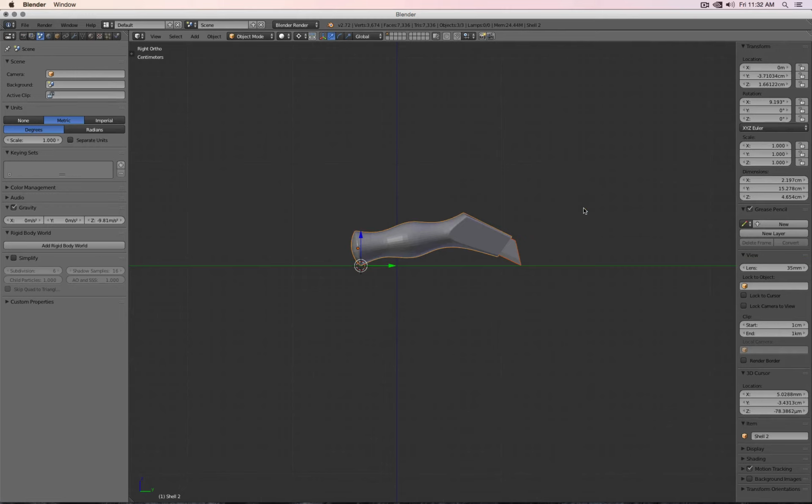position those. The nice thing is, at one point, if for example you always want to reset everything, let's say the rotations, you could select the shell and type in 0, 0, 0, and for X 0. Select this one, 0, 0, 0, and also, whoops, for X 0. And you see, this way you're just overriding everything back to the way the file came into Blender.